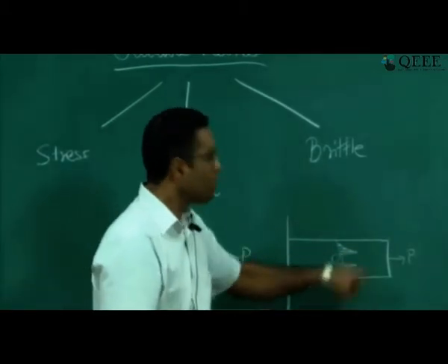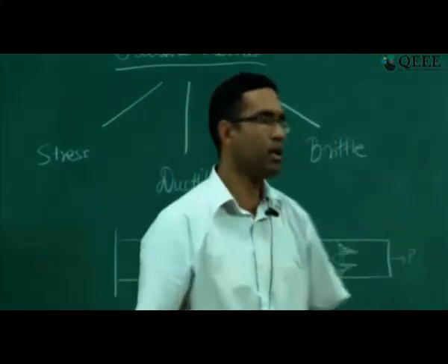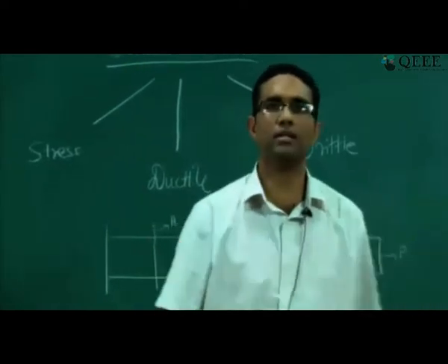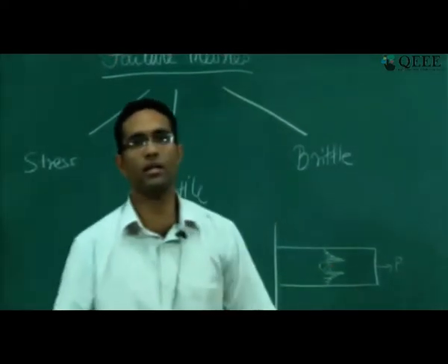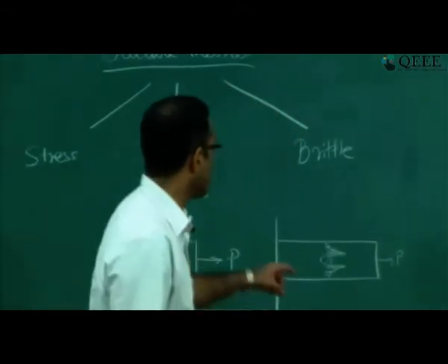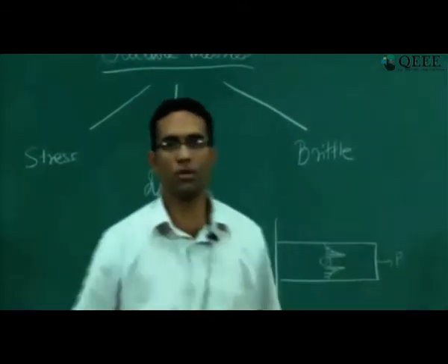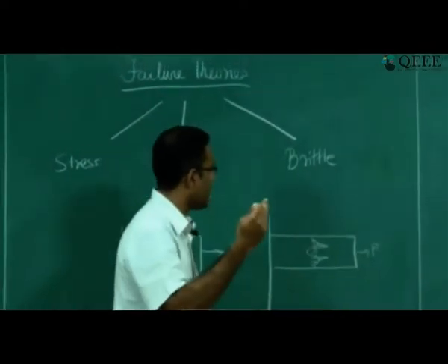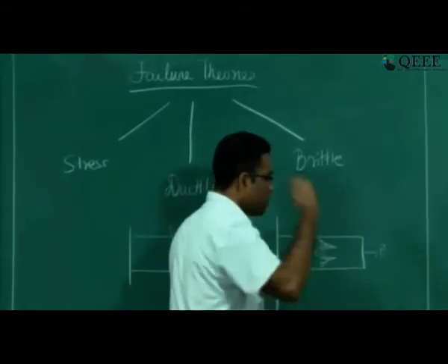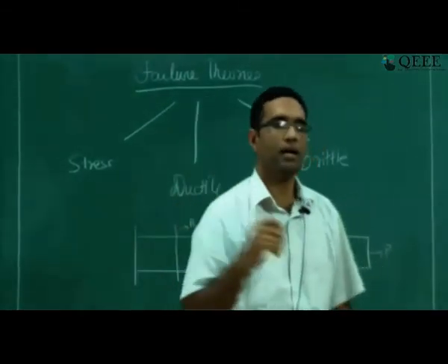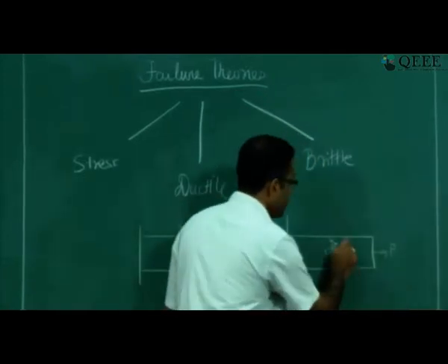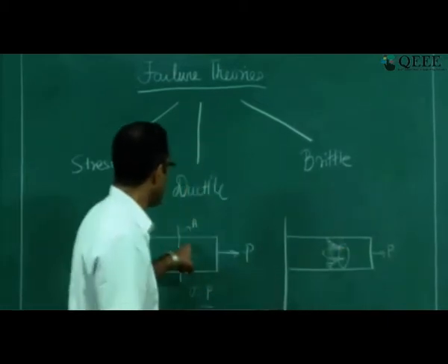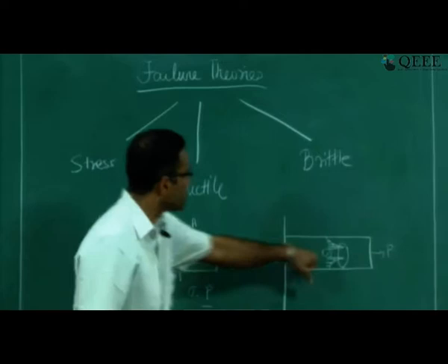Now to account for that stress increase because of the presence of such singularities, every time you cannot do some complicated computational analysis in order to figure out what the maximum stress there is. You want to find out whether that particular spot is failing or not. So we have some back of the envelope or some intuitive way, intuitive in the sense it doesn't come from the air. It basically comes from theories of elasticity, by which you are able to predict by what amount the stress will be higher here when compared to the stresses that are induced in a member without this geometric singularity.